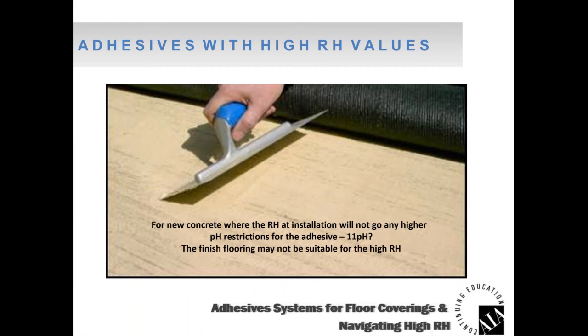Okay, so we know that the adhesive is suitable for a certain RH. We've got to ask the question, is the floor covering suitable for that high RH? Because if it isn't, then we're in trouble as well. If the adhesive is good at 98% RH, that basically means the adhesive is unaffected at 98 RH. That doesn't mean the adhesive is remediating moisture.